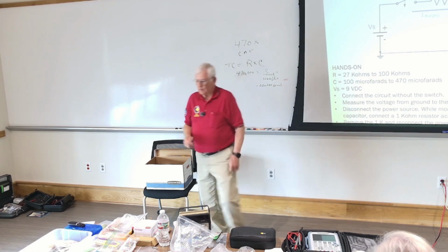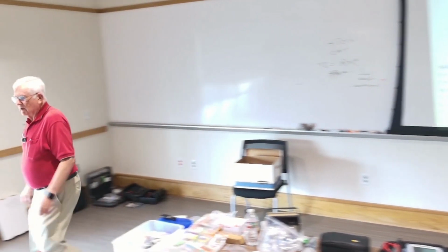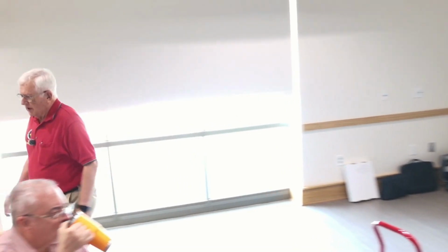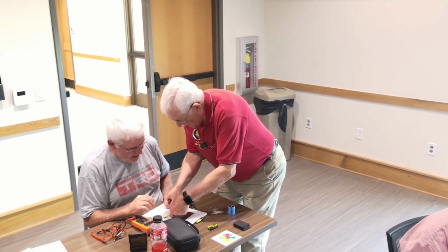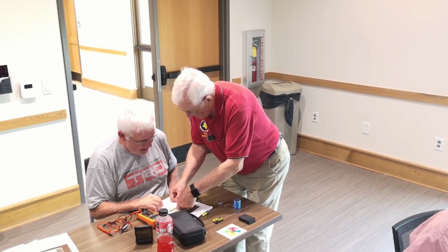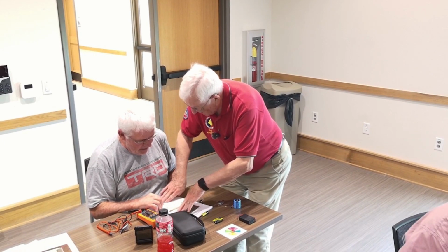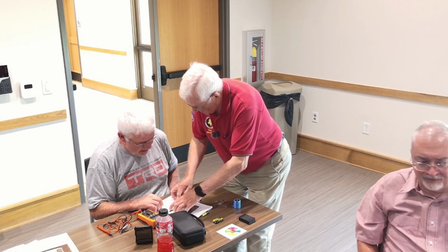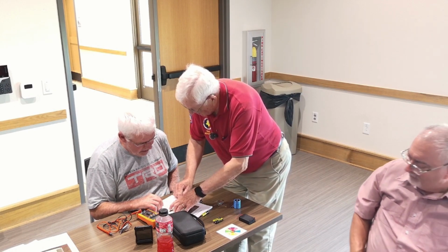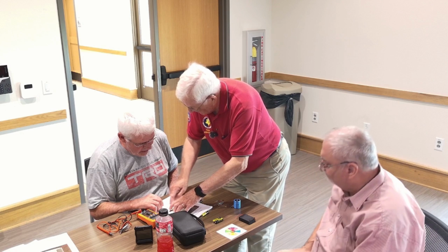I've absolutely no clue how to use a breadboard. Okay, not a problem, we can fix you up. This row of pins are all connected together, but they're not connected to anything else. This row of pins are all connected together, but they're not connected to anything else. Each row of 5 are connected to each other here, but they're not connected to any other rows.